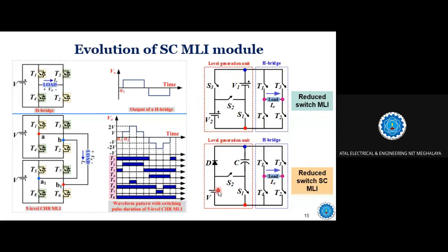In the conventional circuit, it cannot boost the voltage, because whatever supply voltage we have, we get the same output. But here, with V in one single DC source, we are getting the voltage 2V. So we are able to boost it 2 times.